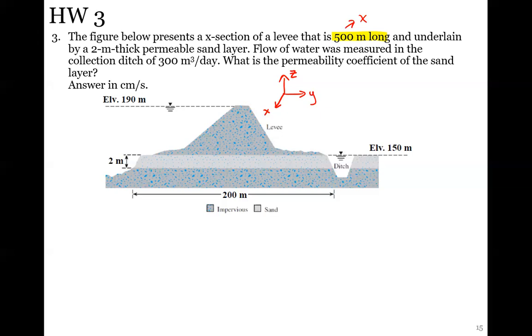So we can measure this by just the pump, like there could be a pump over here, and what is the pump rate that we need to have to keep the water level at a consistent level. This is like how an engineer would actually measure this in the field. So if they have to pump water out at this certain rate, then we can estimate that the water coming in is at that rate, to keep it at a constant elevation.